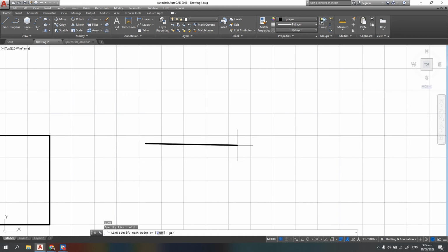There is no word or symbol for angle on our keyboard, and we can't just type the word angle. What AutoCAD uses is the less than symbol, which is on the left side of M, right? You just need to use shift since it is above the comma. Is that right? Yes, it is above the comma. So what you're going to do is shift then comma. That will be your angle. Then since it is aligned horizontally, its angle is 0. So that is like that. Okay.